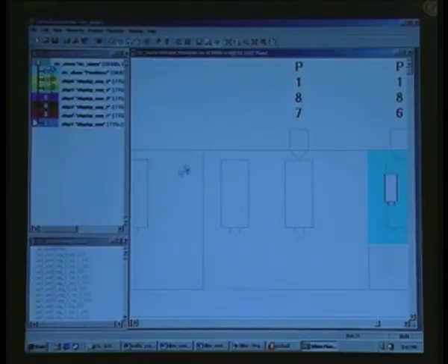Okay. See, if you recollect what I have spoken several lectures before, while explaining the entire design flow, any design is an iterative process. So, you have to run through all the tools, start coding, run through all the tools and repeat this n number of times till you are totally satisfied, both at the simulation point as well as the synthesis as well as the place and route. In spite of running all through, the place and route tool will not put it very efficiently. After all, no tool can equal human intelligence.